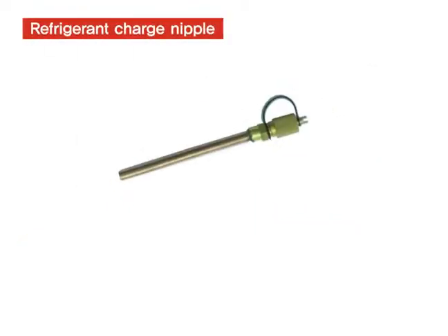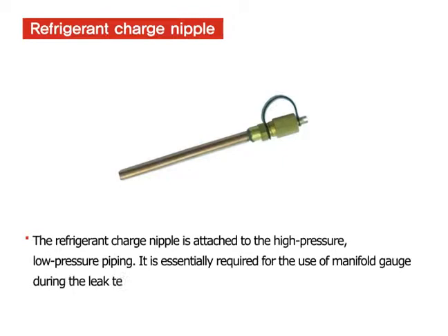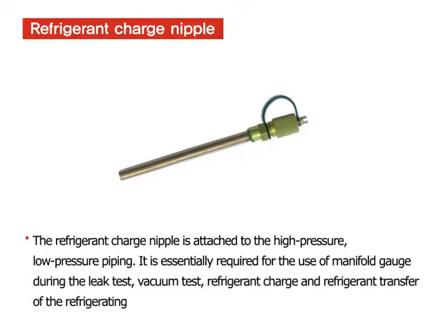The refrigerant charge nipple is attached to the high pressure and low pressure piping. It is essentially required for the use of manifold gauge during the leak test, vacuum test, refrigerant charge, and refrigerant transfer of the refrigerating device.